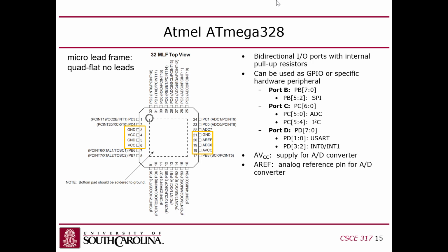But when you look at the pins, you notice that you don't have an external memory interface. There's no DRAM interface on this thing at all, obviously because it relies on its internal memory. Also, all the pins on the chip, except for these 8, you'll see there's 2 power, 2 ground over here, another ground, and then analog reference and analog power over here.